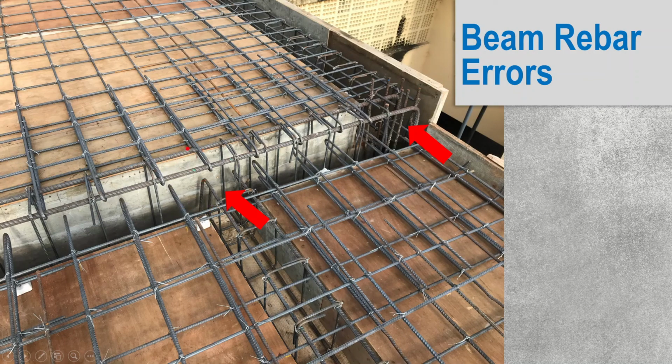You can see here they have not provided the shear links for the beam. Here there are no shear links for the beam, especially when you have a secondary beam supported on the primary beams. You have to provide additional links as hanger reinforcement, but they haven't even provided the regular links. Therefore you have to keep in mind that there should be an additional requirement for shear links for beam to beam joints. You have to provide the additional shear links at the primary beams during the construction.